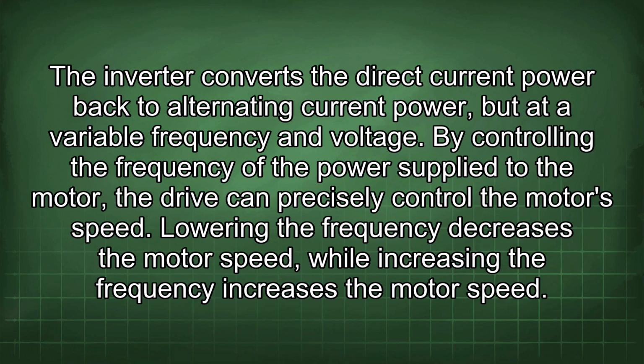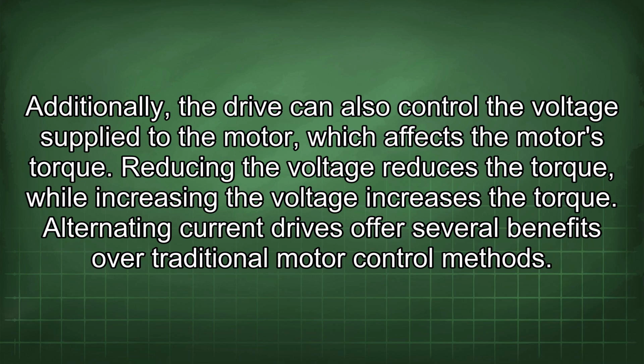Lowering the frequency decreases the motor speed, while increasing the frequency increases the motor speed. Additionally, the drive can also control the voltage supplied to the motor, which affects the motor's torque. Reducing the voltage reduces the torque, while increasing the voltage increases the torque.